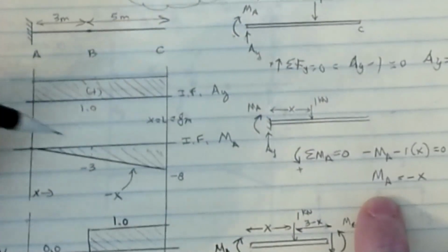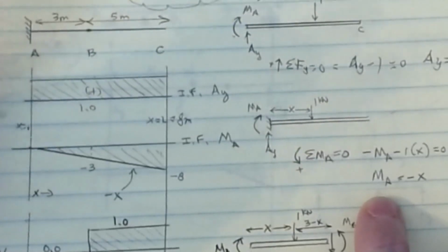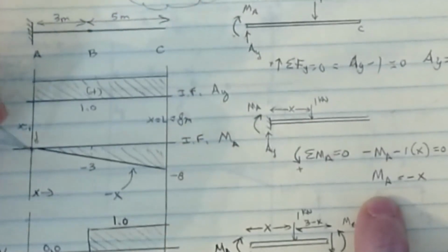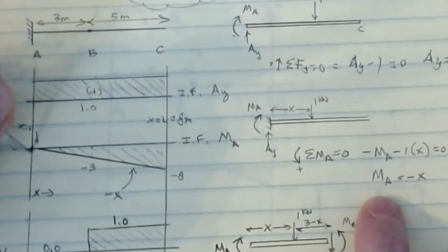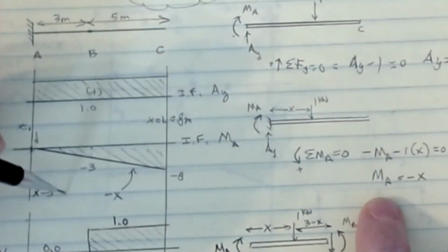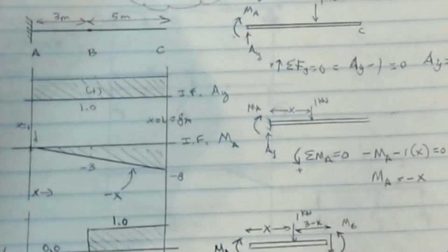Now, like I say, this one's a little interesting. It's almost the reverse of the shear and moment diagram. Because if I put the point load here at that support, it all goes directly into the support, and there's no distance associated with it, so the moment here is 0. Whereas the reaction is still the 1 kip load. So it's this counterintuitive look. I think I struggled with this when I was first learning this. It was hard for me to wrap my head around. Okay, and so that's what we have.